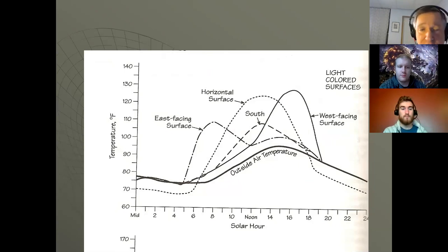That's what happens. And so there's a lot of information in this diagram. Now this is for a light colored roof. And as I flip to the dark colored roof, you're looking at the effect of absorptivity. So the light colored roof has low absorptivity, and you see this, what's often called the cooling load temperature difference, CLTD, is 120 degrees. It's very high. And if I go, I don't have a dark colored roof here. Where is it? Oh, I don't know what I did with it. Okay, well, it's higher. It's a lot higher. It's about 40 degrees higher. Same thing, everything's exaggerated.